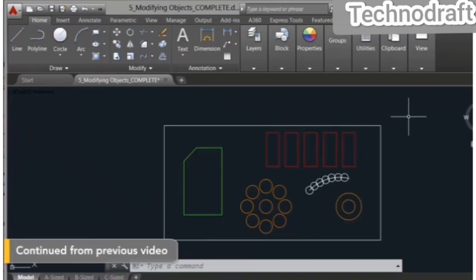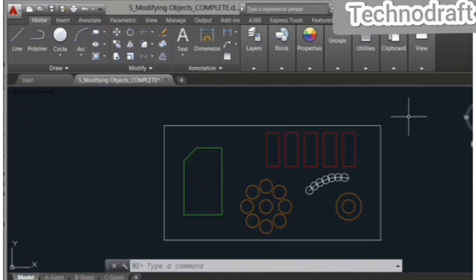We are now going to look at the trim and extend commands available in AutoCAD and the sorts of things that you might be expected to do for your AutoCAD professional course. Now we are going to work with these rectangles going across our little plates that we are creating. What we are going to do is convert each of these rectangles in essence into 3 buttons, and they are going to be the control buttons on this little control panel that we are creating.